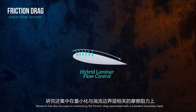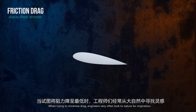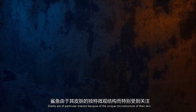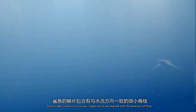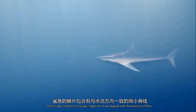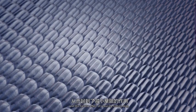Research has also focused on minimizing the friction drag associated with a turbulent boundary layer. When trying to minimize drag, engineers very often look to nature for inspiration. Sharks are a particular interest because of the unique microstructure of their skin. Shark scales contain microscopic ridges, which are aligned with the direction of flow. These ridges modify the turbulent boundary layer in the near wall area, and this has the effect of reducing friction drag.